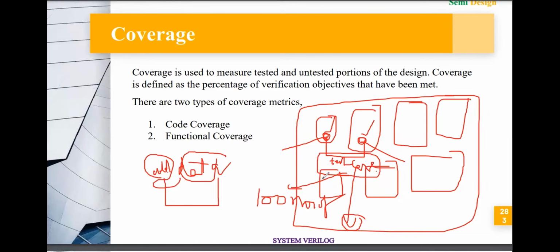If you got coverage of 99% also, our project is not done. Not even one bin, because in terms of 1,000 bins or 2,000 bins it will nearly have, those bins also we need to cover. That is the main coverage. Once it reaches 100%, the total functionality is working correctly. If even one bin is left, some functionality is missing.